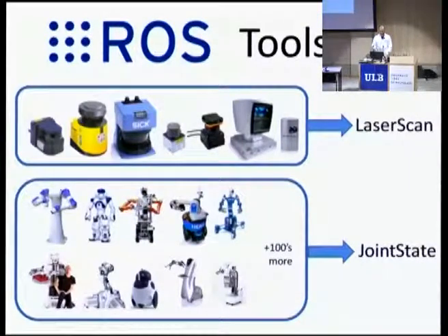There's a thing on the top that spins around, and then they typically output a custom binary message. This is a picture of seven laser rangefinders. They all have their own custom binary protocol. The nice part, though, is that now everything has been bridged to ROS. So all these things output laser scan messages. If you turn it on, start up ROS, and start up the laser driver, you're going to have laser scan messages coming out, which is general enough to define the output of all those scanners.